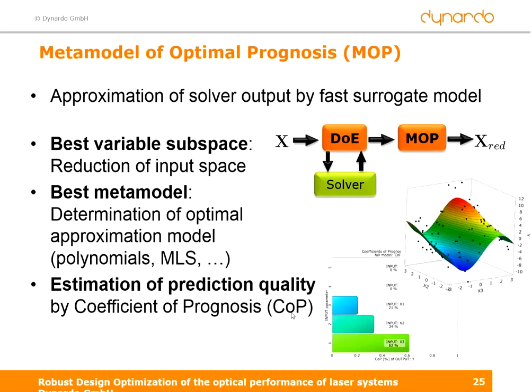And this fitting is estimated with a coefficient of prognosis, which means we have a particular coefficient that helps you to get models that can also predict points in the design space, like shown here maybe, where no design point has been calculated, but the model is able to approximate it perfectly, which is verified with this coefficient of prognosis.